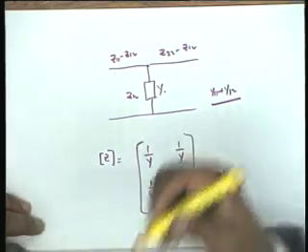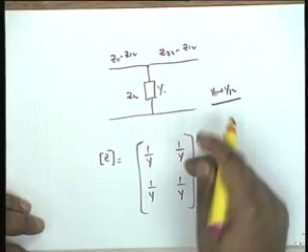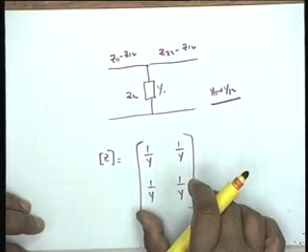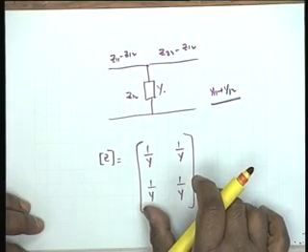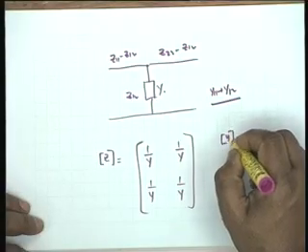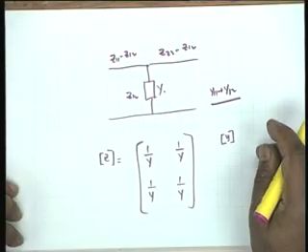This is also one of the reasons why the y parameters do not exist. The determinant of this is infinity. This is a singular matrix, alright. The determinant is infinity, and you remember that the y matrix determinant is 0. So it's a singular matrix.